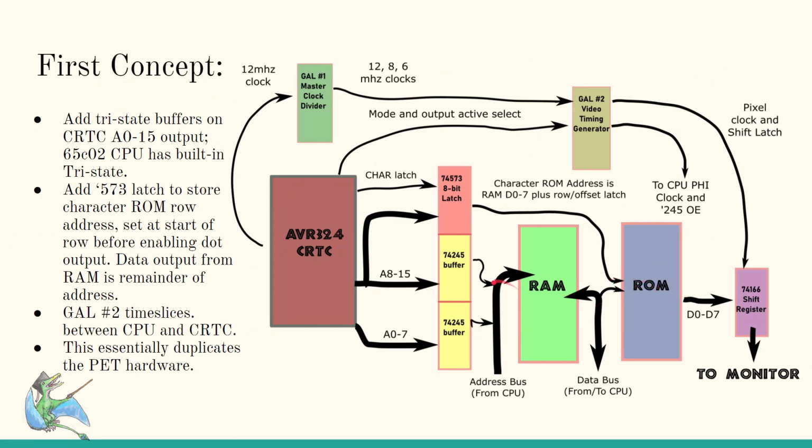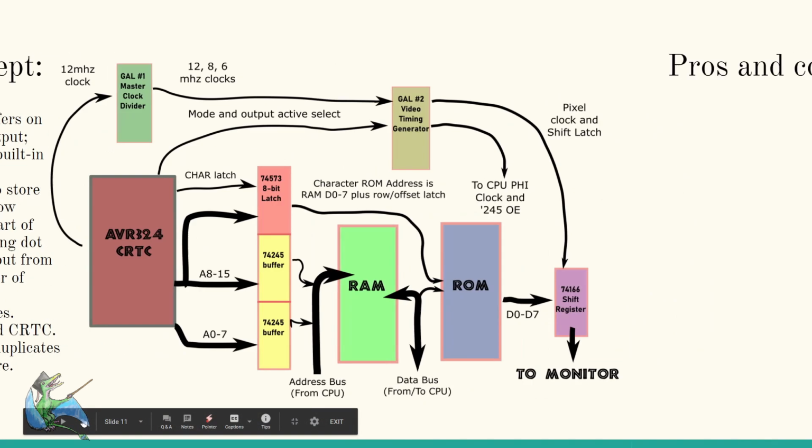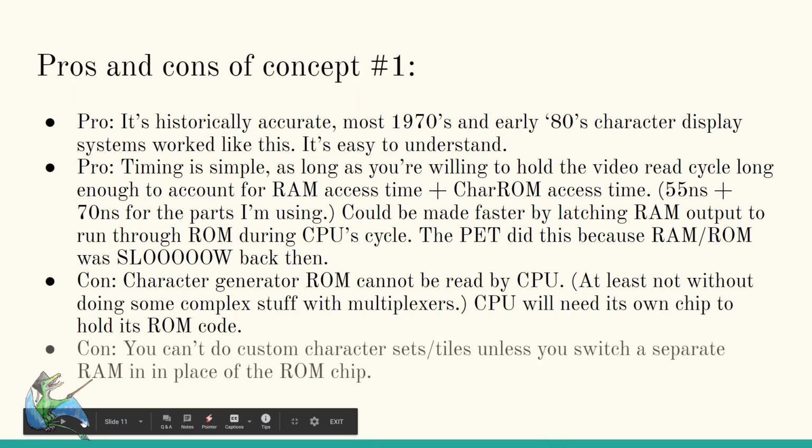The content that comes out of the RAM is going to be a number from 0 to 255. You could just have a section of the ROM, which you would select by the latch, where 0 to 255 comes in this side, and 0 to 255 comes out the other side. Just let it go through the ROM. That would be wasteful back in the day, but of course, these days memory's cheap, so we don't mind throwing away that.